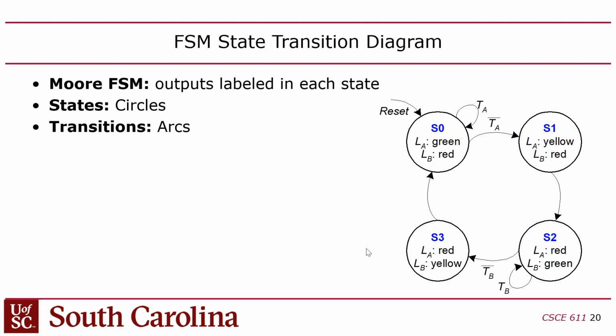So in this case, the clock period has to be set up to be the amount of time that the yellow light would be on. So this would be like a clock period of, say, I don't know, 5 seconds, 10 seconds, something like that. So it'd be a very slow clock, right? In reality, you'd have some kind of external timer, and that would signal. You'd wait for the timer to reach some point, and that way you could run the clock faster. But in this case, we just adjust the clock to be the yellow light time,